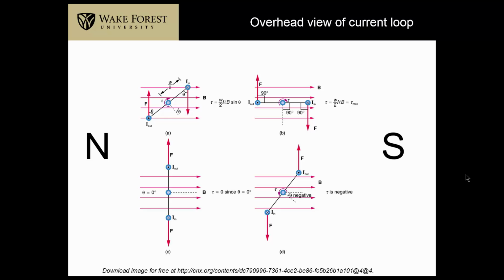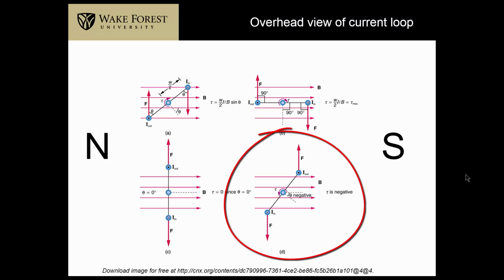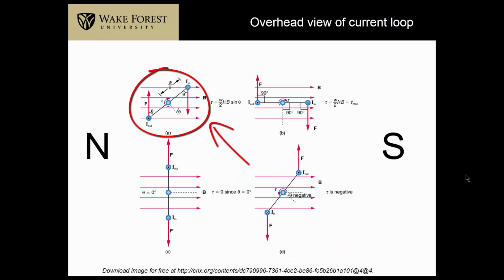Then instead of having a counterclockwise torque in this last situation, we would have our currents reversed, our forces would be reversed, and we would be right back to our original situation. We would continue to have a clockwise torque, and we'd go another half turn. If we reverse the current again, we would go another half turn.